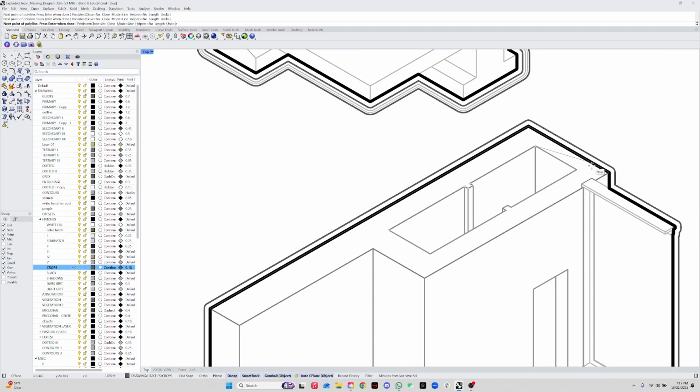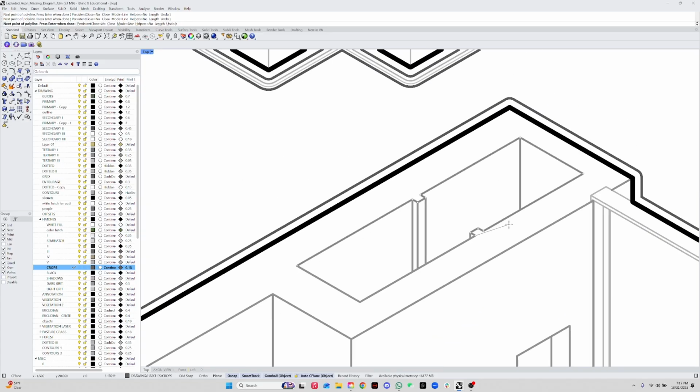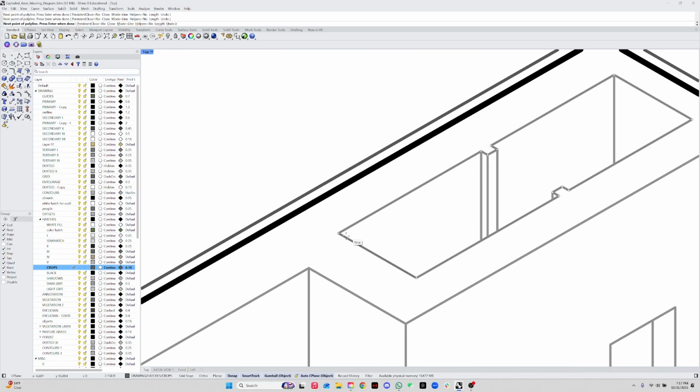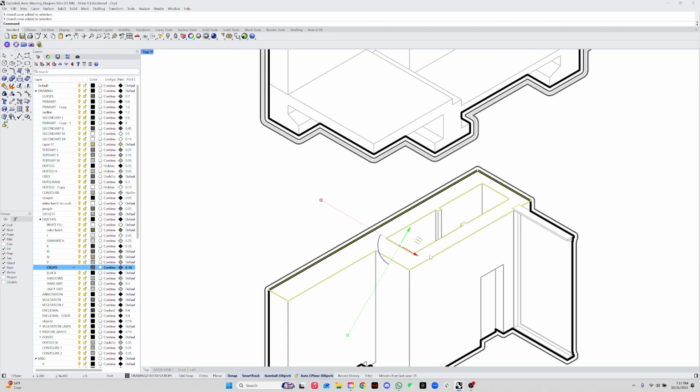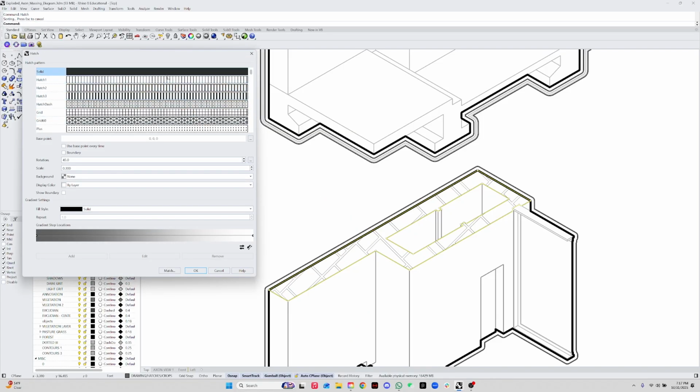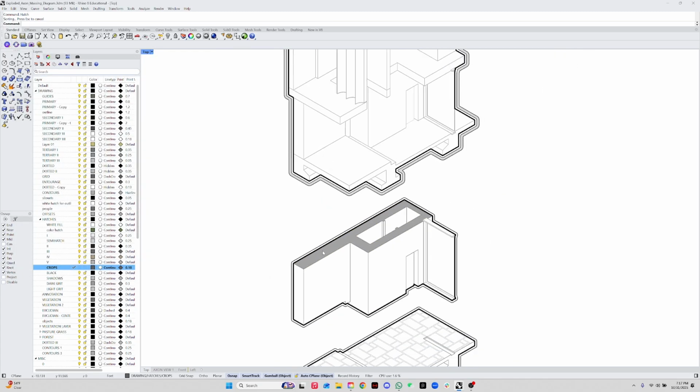That's if the curve boolean is not working and you can't really find where the line is. The same amount of time it's going to take you to fix this is the same amount it takes to do this very quickly. So I'm not opposed to drawing this little curve again. Now I have that, I'm going to group it and hatch. And then here I might just choose a solid, right? And then you can have a separate layer for that.